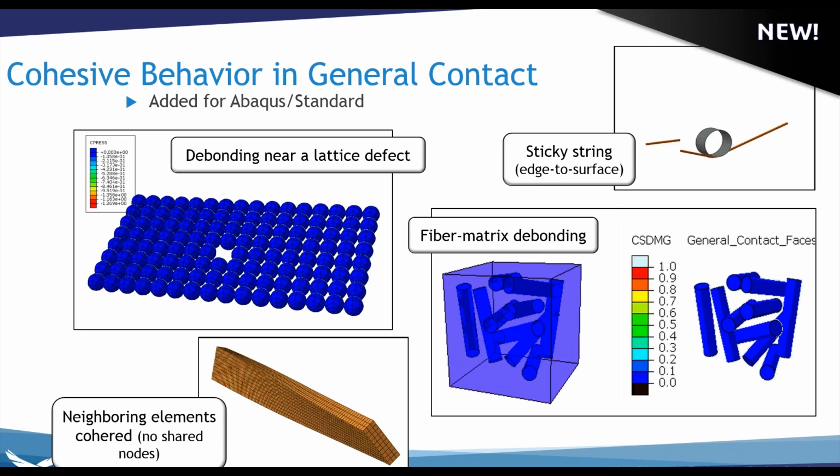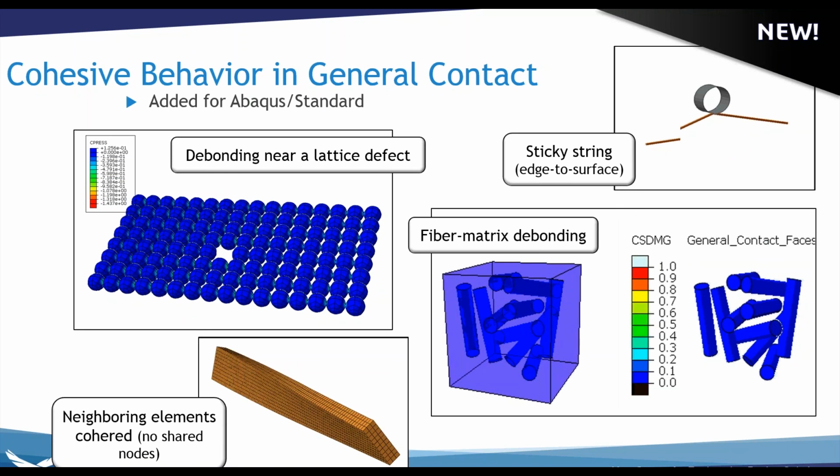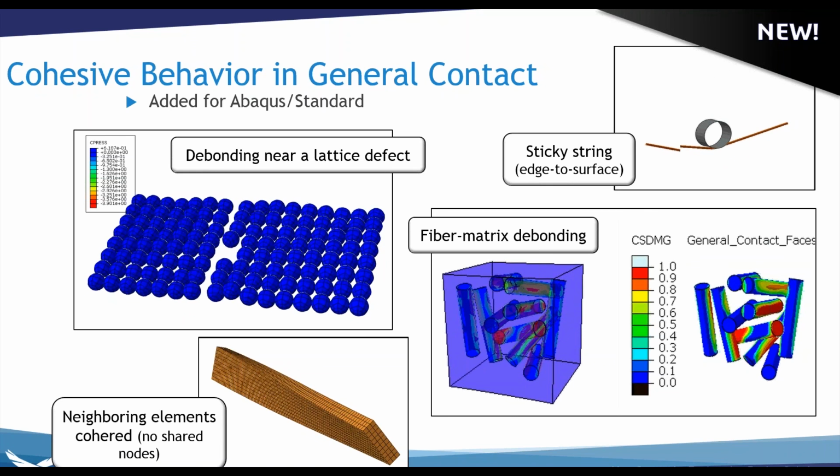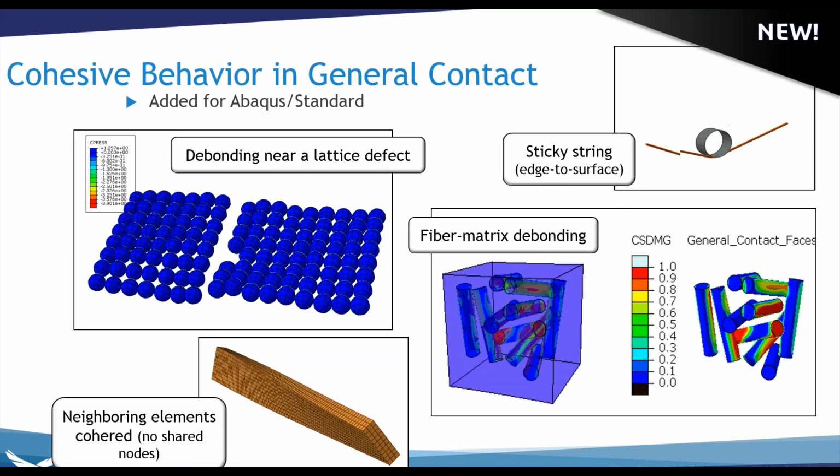So one area that this could be key is if you want to pull in a finite element model from another code where they're all separate in nodes. If you don't want to merge them for whatever reason, you can use that.